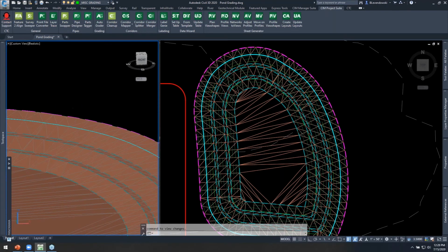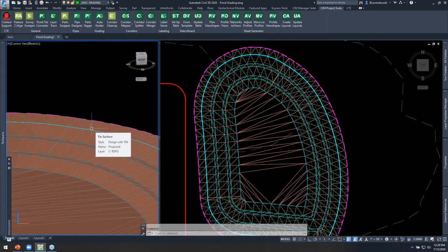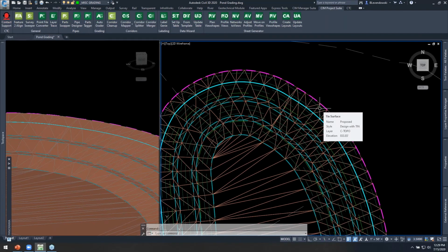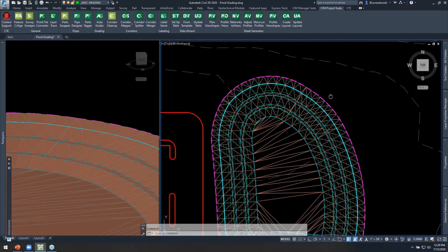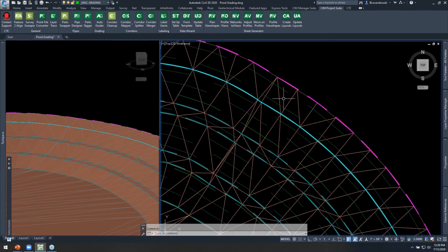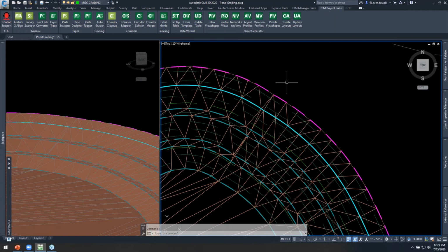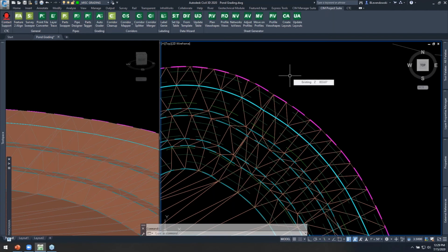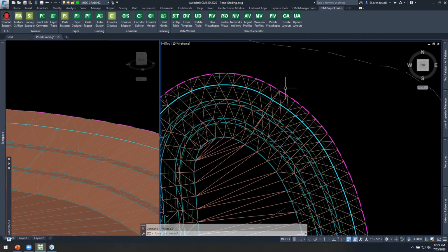So what if I want to put a spillway in here? Well, again, it's one of those manual things. I want to decide where exactly I will put that, okay? What does the elevation look like, that sort of thing. And what can be real easy to do here is to simply draw a single feature line for your spillway. So we're going to draw a single feature line right about in here. And then we're going to take advantage of feature line style hierarchy again, so that it basically puts a cutout into our berm here. And then from there, we're going to daylight to existing grade, and we'll tie in from there. Okay.